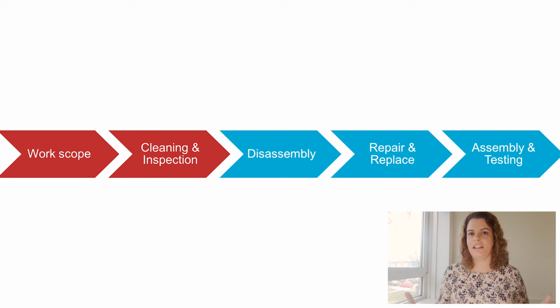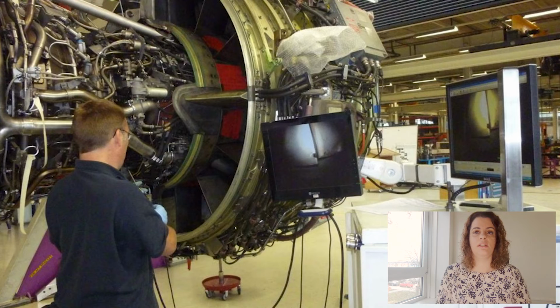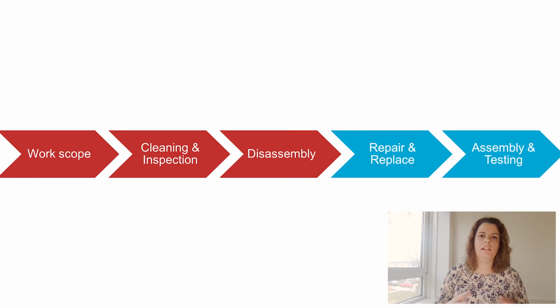Then comes the cleaning step, where you put the engine into several liquids to perform what they call a bath. So they basically clean the interior and the exterior of the engine. And then they're ready to perform an initial visual inspection, where they use a small camera that goes inside the engine and tries to figure out if there's something wrong with the structure, or some corrosion, or something that is not as it should be.